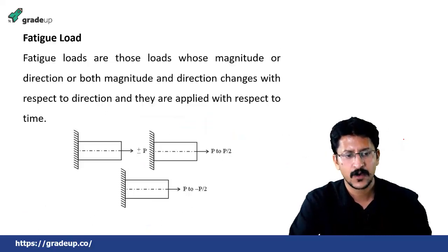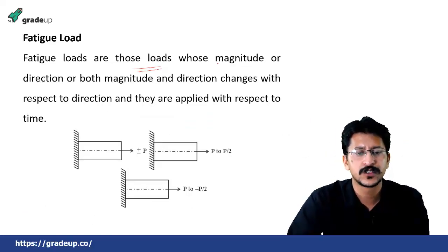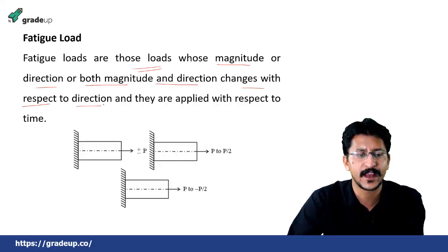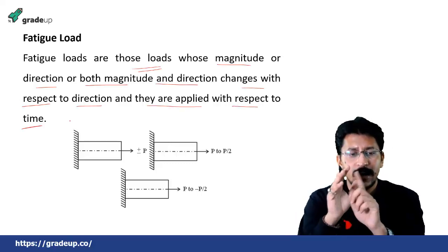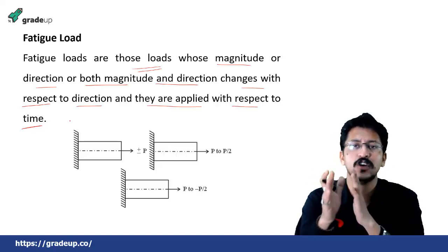Okay, next, fatigue load. What is a fatigue load? Fatigue loads are those loads whose magnitude or direction, or both magnitude and direction, change with respect to time as they are applied. So their magnitude is changing with respect to time and their direction is also changing.